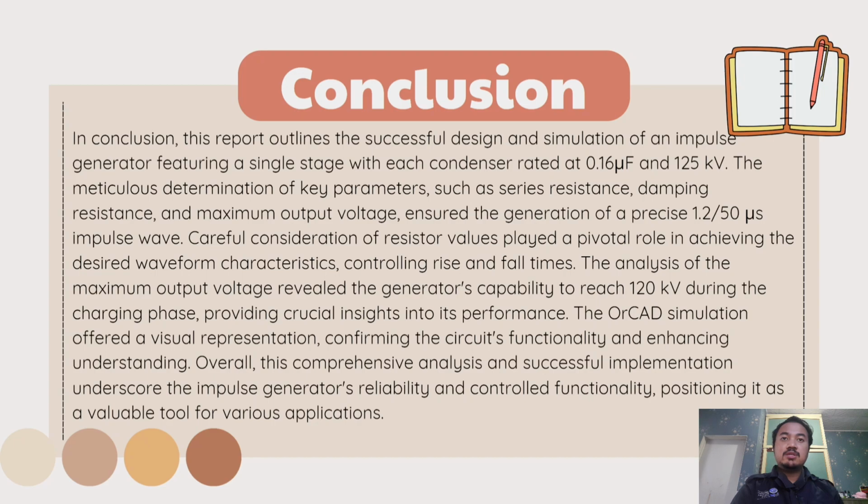Careful consideration of resistor values plays a pivotal role in achieving the desired waveform characteristic, controlling rise and fall times. The analysis of the maximum output voltage revealed the generator's capability to reach 120 kV during the charging phase, providing crucial insights into its performance.